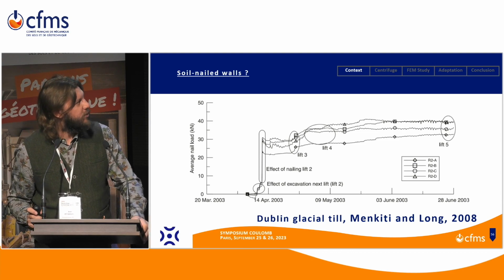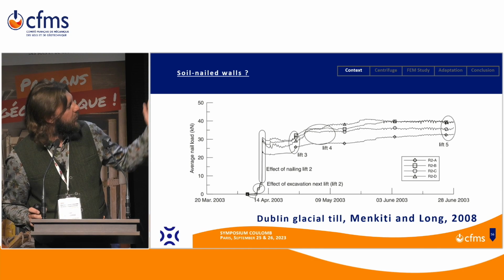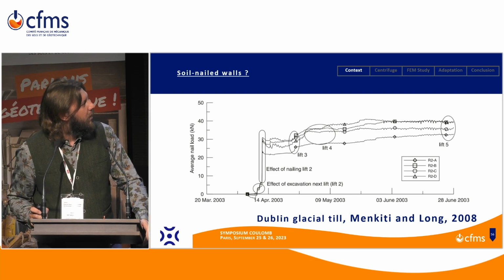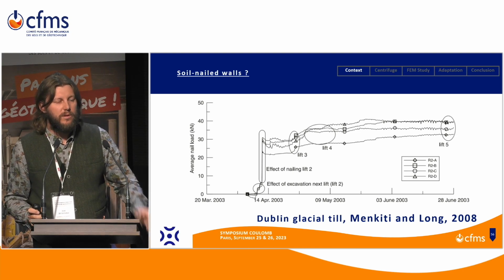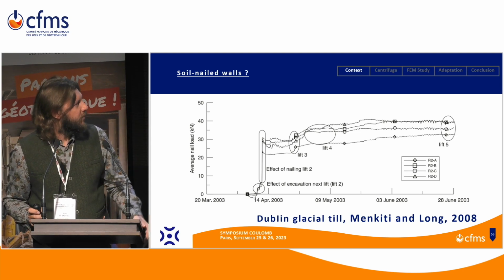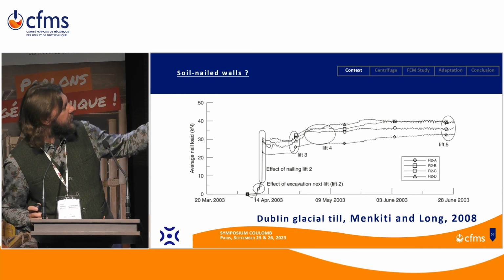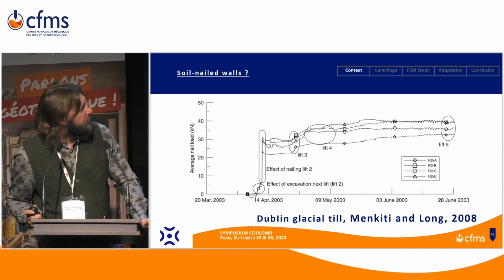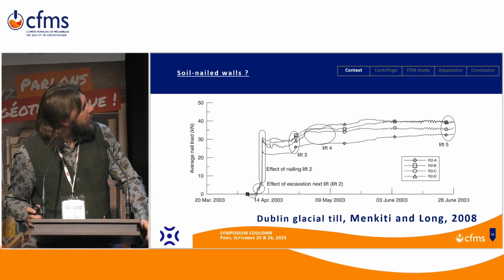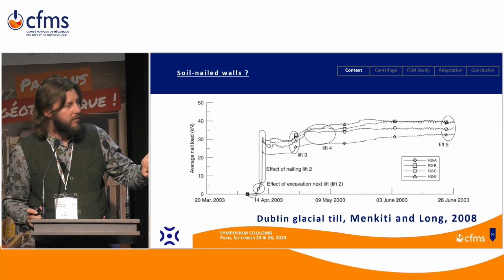Here's just an illustration of what I said before. It's a project done in Dublin, where they monitored, during the construction of the metro project, the tension in lots of nails. You can see that once the nail is put in place, its tension is 0. And the major effect is done when you excavate the second lift.